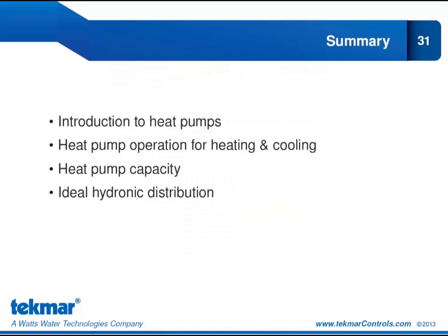And lastly, we looked at what type of hydronic distribution system is well suited for a geothermal system design. We eliminated typical radiator and baseboard installations because those require higher water temperatures, and focused on a radiant installation. And it just so happens that radiant systems work best at low water temperatures, and heat pumps offer their highest efficiencies at low water temperatures.